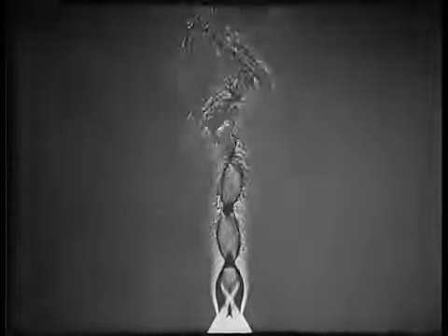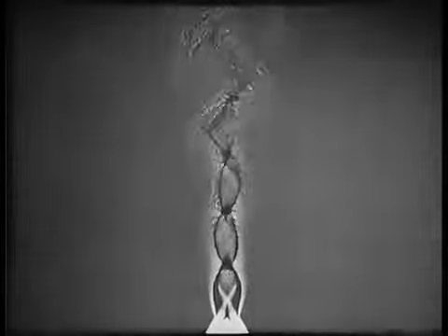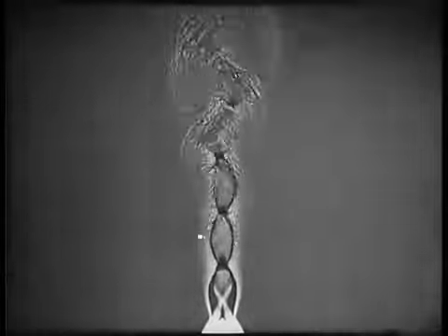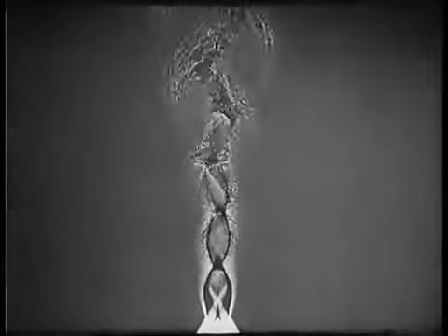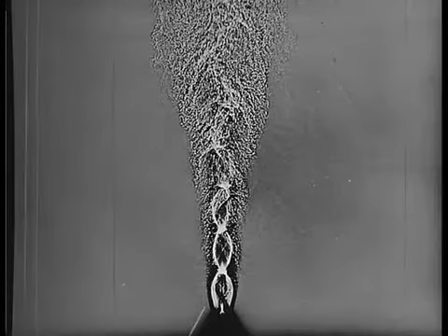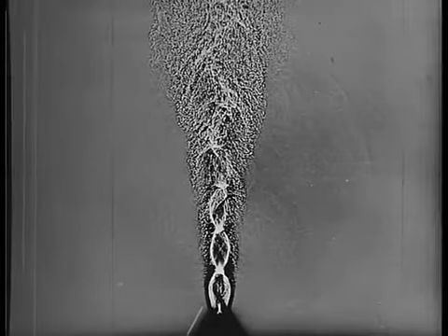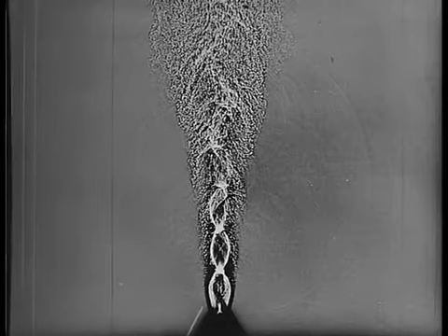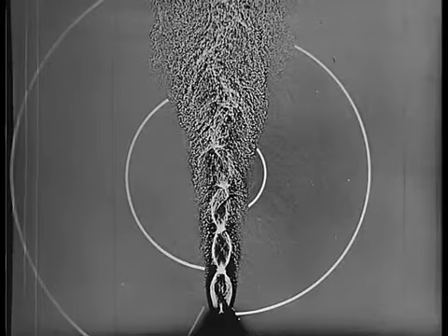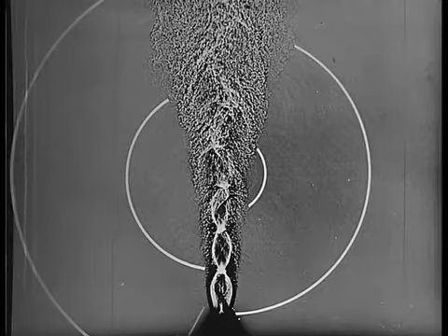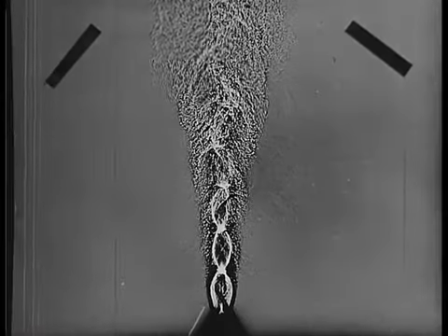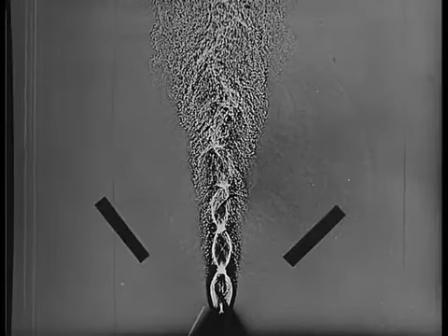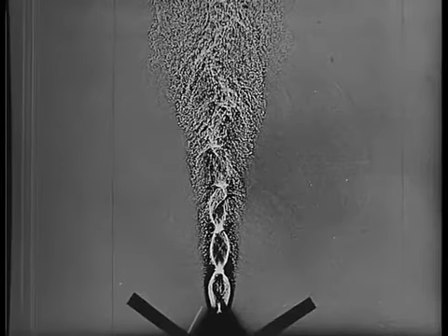To obtain more detailed information on this relationship, which may reveal the feedback loop at the same time, experiments were carried out as follows. If the feedback loop lies partly outside the jet, it seems reasonable to assume that the sound pulses themselves convey the feedback signal. To verify this supposition, reflectors were placed outside the jet, taking care not to influence the jet aerodynamically.